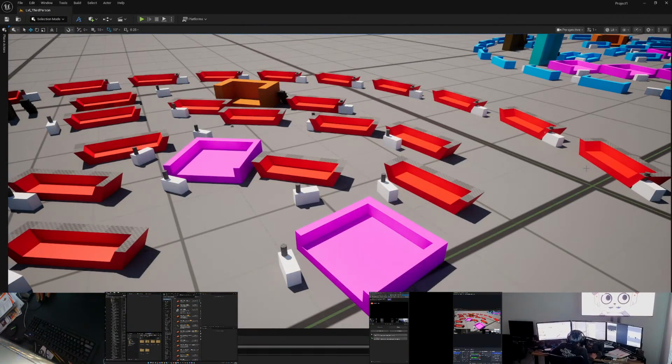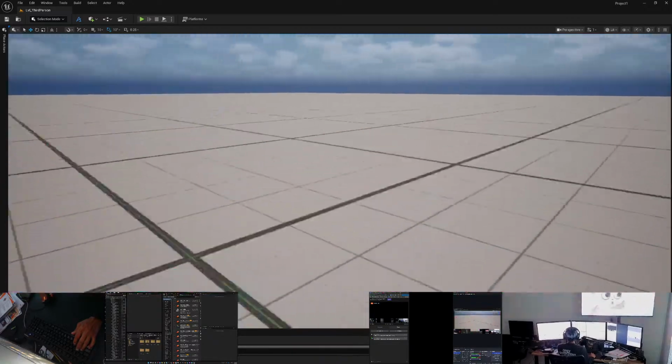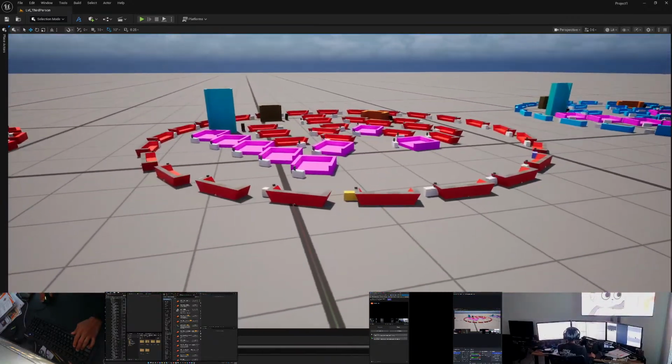But long story short, with SketchUp, you want to get familiar with how components work, and you want to work with components for every asset that you have in your scene, and you want to keep those assets separated throughout the entirety of your design process, and keep assets within components, and then modify the axes of each component. For every item that's duplicated in your scene, it should be a component.